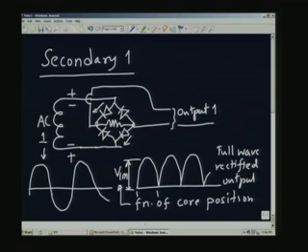This corresponds to this, I will say T by 2, this corresponds to this T by 2 here, and this will correspond to this half cycle, this will be T by 2. So, something like this. So, this portion has become this portion now, it has been inverted or rectified. So, that is what the full wave rectifier is. In the sketch which I showed in the slide, if I had only half wave rectification, the alternate ones will be missing, these will be missing.